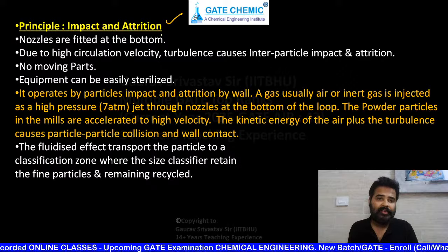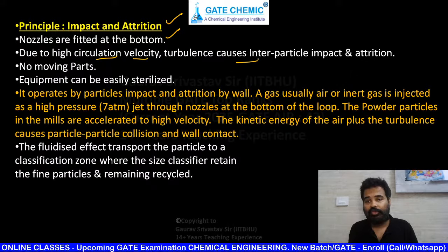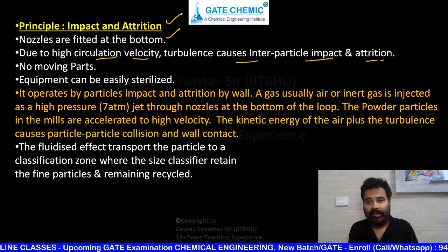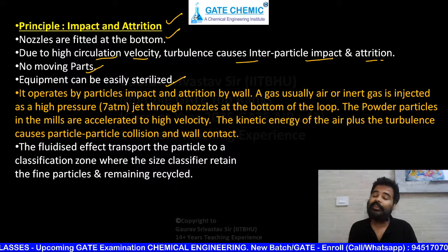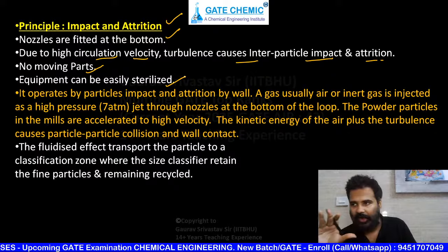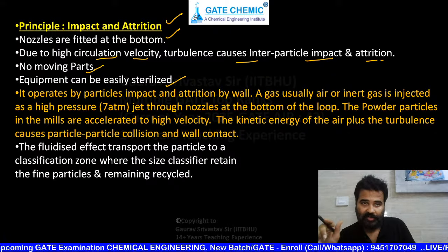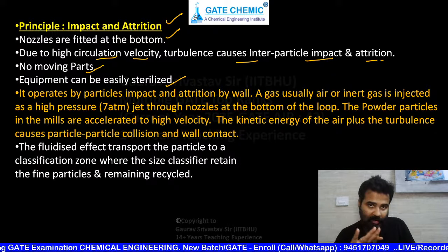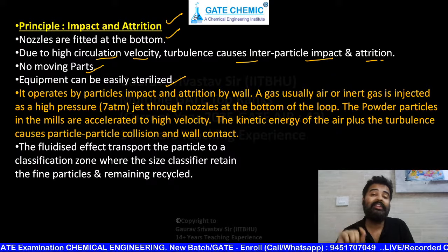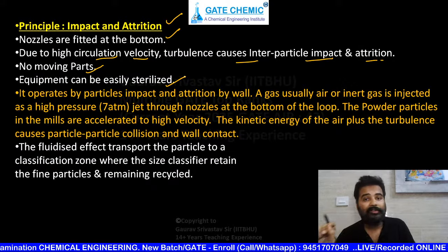Principle: impact and attrition. Nozzles are fitted at the bottom. Due to high circulation velocity, turbulence causes interparticle collision and attrition. No moving parts, very easy. Equipment can be easily sterilized. Sterilized means what? Sterilization: whatever cleaning is inside, bacteria you want to remove, that is sterilization. Why is sterilization easy? Because no moving parts are present. If no moving parts are present in any equipment, then the cleaning is very easy.